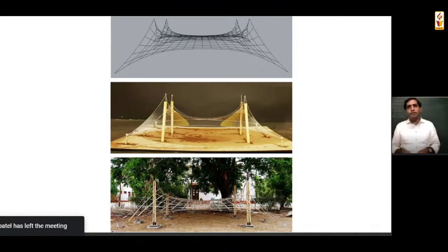the split bamboo, if it is this split bamboo, you can only bend in these two directions, which means it can take this form. It can take this form, but it cannot rotate. Now, when it cannot rotate, whether I'm making a synclastic, anticlastic, any kind of form, these are anticlastic forms, we soon started realizing that, apart from the grid, for some of the forms, in order to achieve the form, there will be torsion in the individual split.